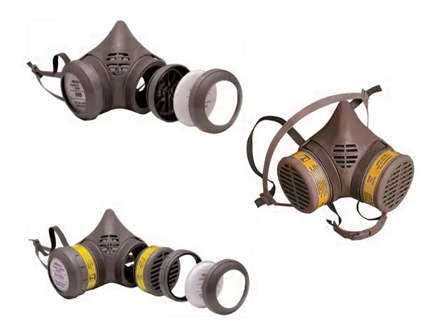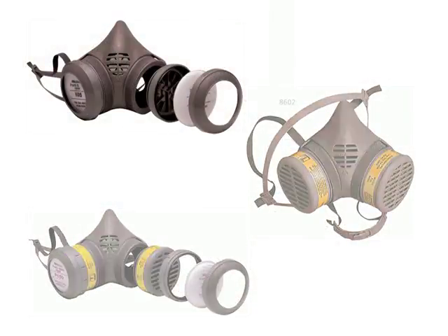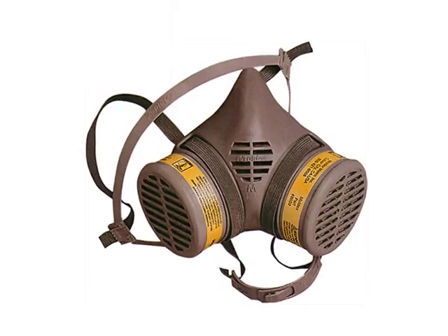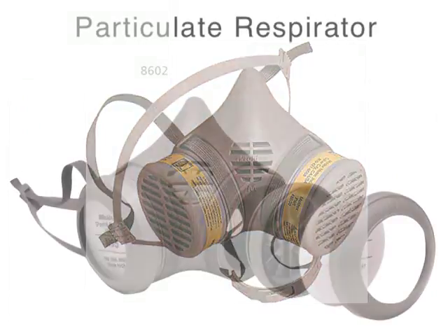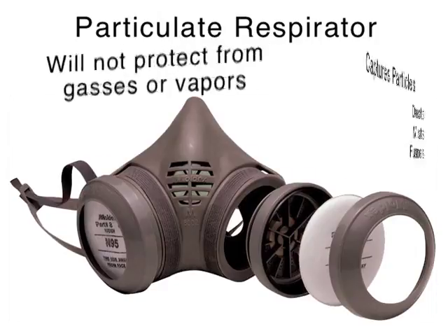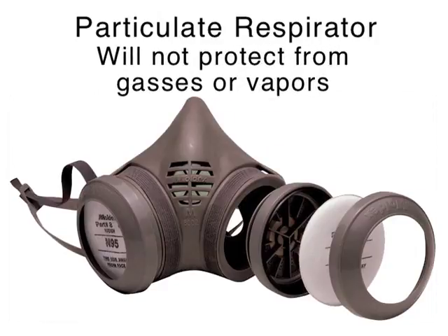There are three different types of air purifying respirators: a particulate respirator, a combination respirator, and a gas and vapor respirator. A particulate respirator captures particles in the air, such as dusts, mists, and fumes, but will not protect you from gases or vapors.